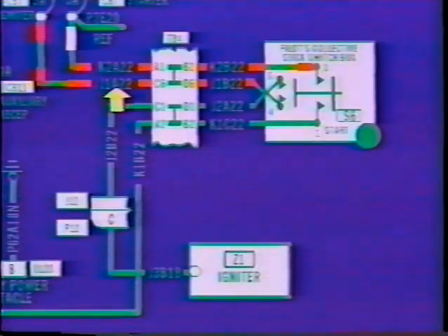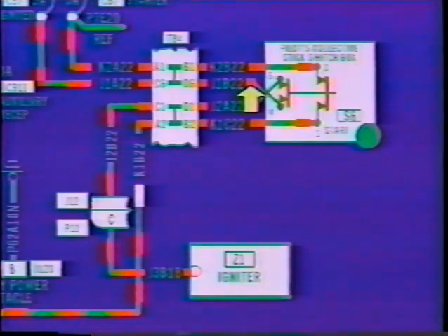Follow that wire to the pilot's collective stick switch box. Without the starter switch depressed, power from the bus is now laying in wait at the switch. Now, depress the starter switch. Continue the trace through the starter switch. Notice the exciter has now been energized. The exciter in turn energizes the igniters and completes this circuit.